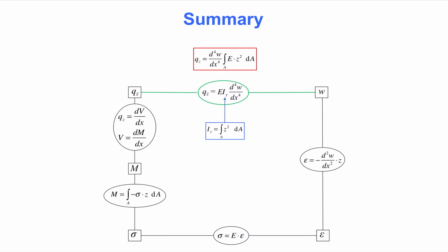The more general differential equation for beam bending is shown at the top of this slide, marked with the red color. However, there is another way to deal with this problem. For composite cross-sections, one approach is to first retain the original differential equation and then to select a reference value of the Young's modulus. Now, assume that all parts of the cross-section have that E value.